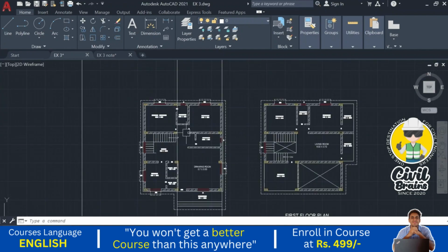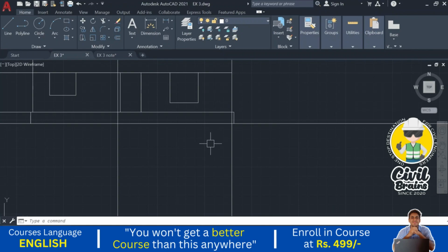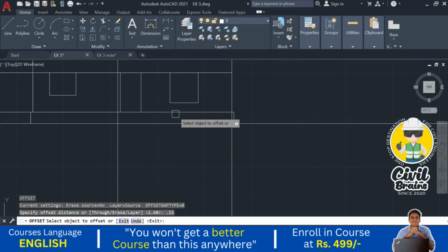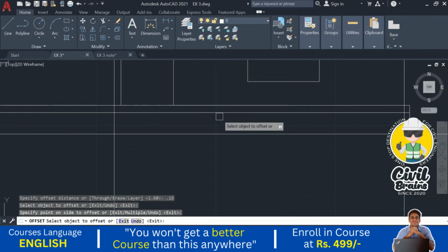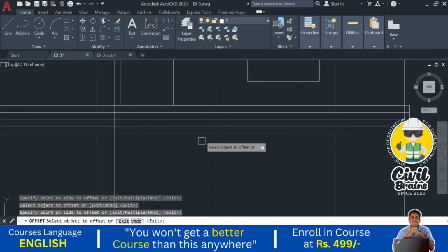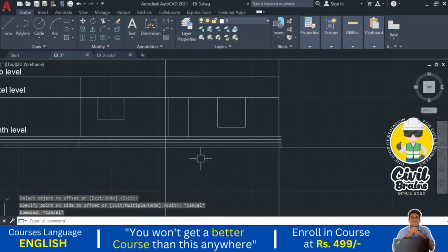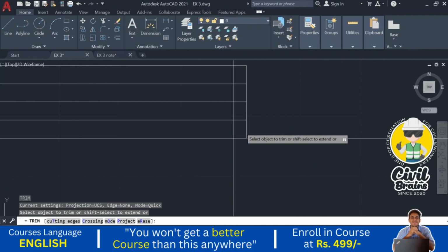Okay. So here I am considering the depth of the step as 0.15 meter. I just go to the offset command and 0.15, that is the risers 1, 2, 3 and 4, and just trim the extra parts.